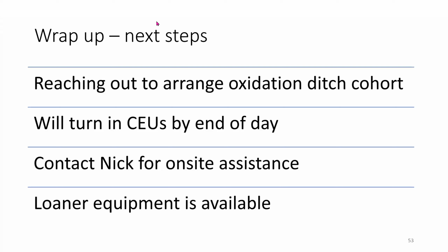So if you have a significant dissolved oxygen, but a zero ORP, what that means is your plant's dead. It means that the oxygen is being put into the wastewater, but the organisms aren't using it aerobically.